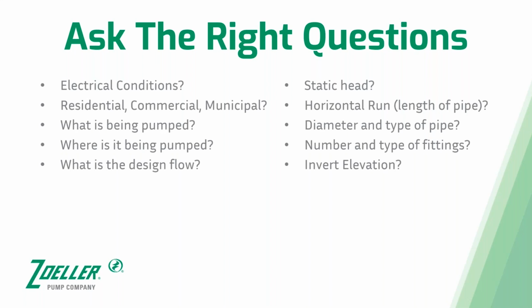And then lastly, you need to know what your invert elevation is. This doesn't necessarily go into pump sizing, but this will help you in determining how deep your enclosure is going to be in order to have enough storage for that pump to operate correctly.